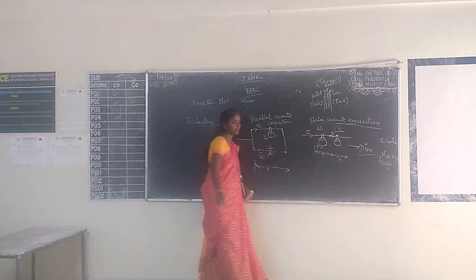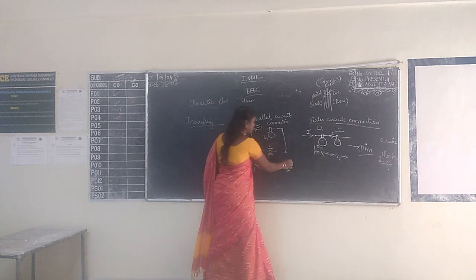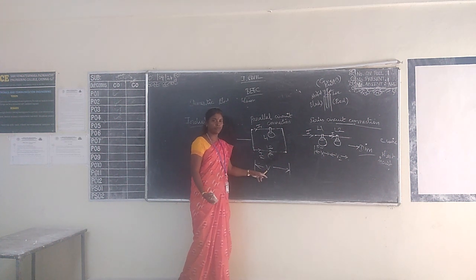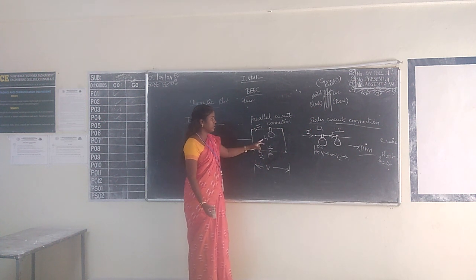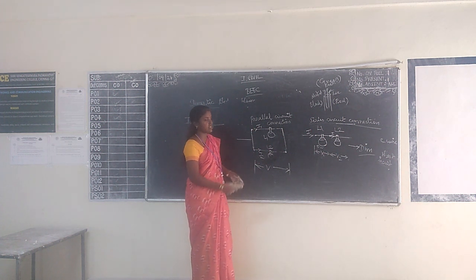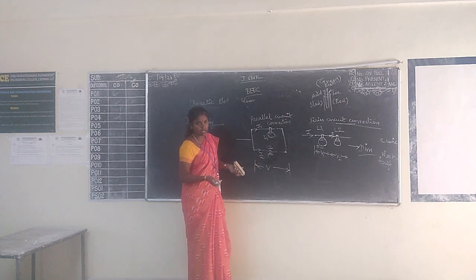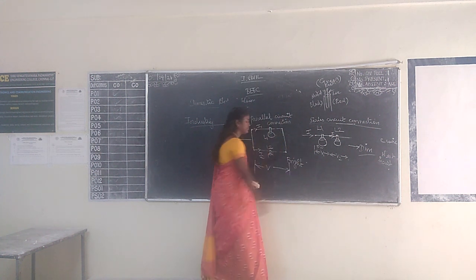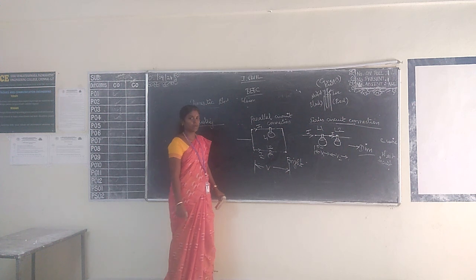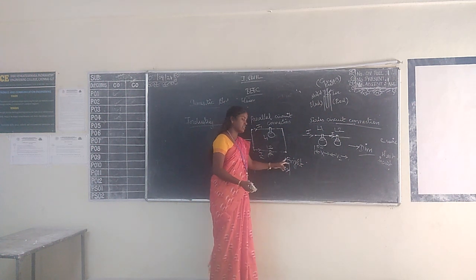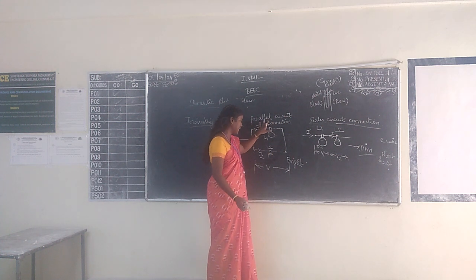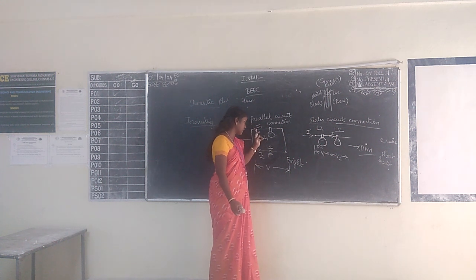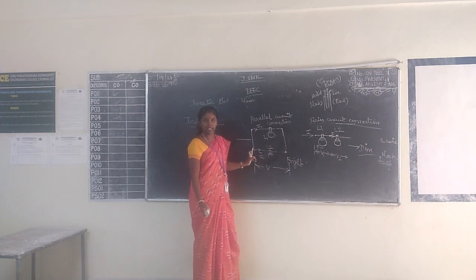So V and V. We are going to measure the voltage in lamp 1 and lamp 2. So here the voltage will be the same. Okay. So when you are connecting the two different lamps using parallel connections, there will be no variations in the voltage. So both the bulbs are glowing brightly. Isn't it? Now do you understand why it is glowing brightly? Since for parallel connections, the voltage will be the same in both the lamps, and the current will be different, I1 and then I2.